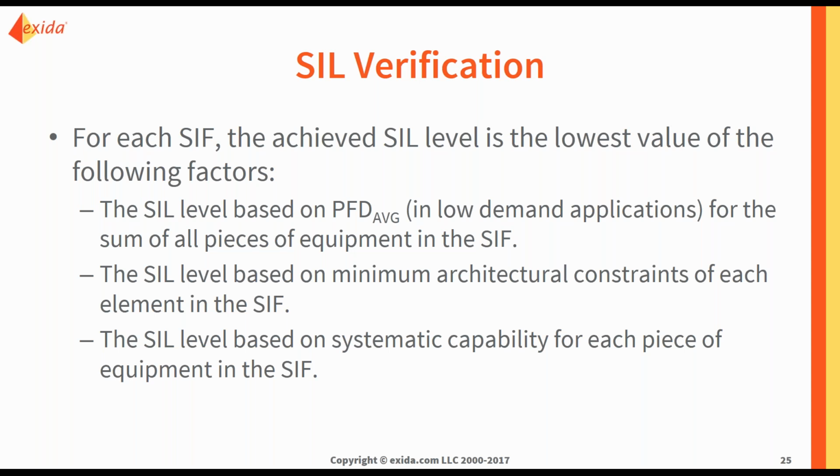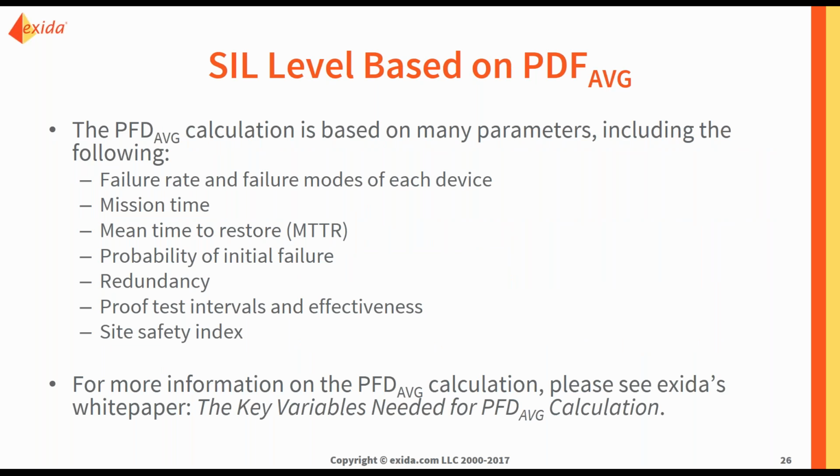So as we know, our safety instrumented function has a pressure transmitter, a logic solver, and a valve. We're going to take a deeper dive into each of these factors, but the point here is to specify your equipment such that the SIL level of each of these factors is matching your target SIL.